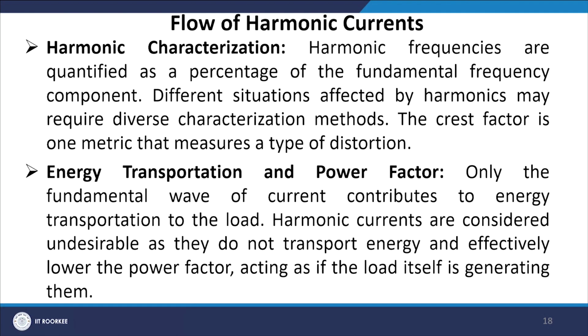Distortions are majorly seen in the case of loads that are connected with nonlinearity as well as power electronic devices. Only the fundamental wave of current contributes to energy transportation to the load. Harmonic currents are considered undesirable as they do not transport energy and effectively lower the power factor, acting as if the load itself is generating them.